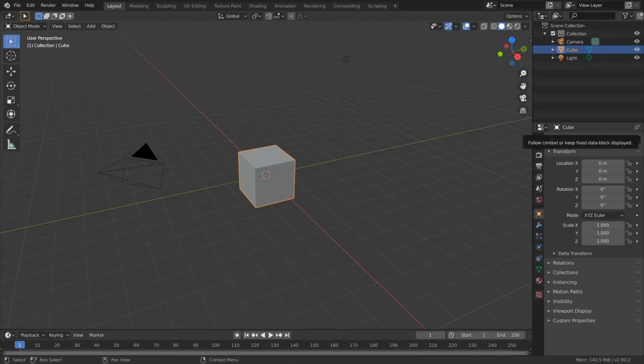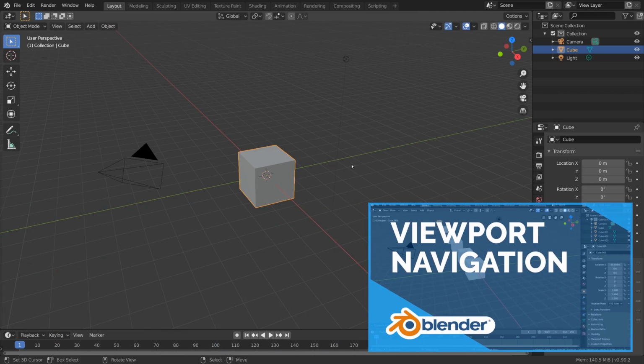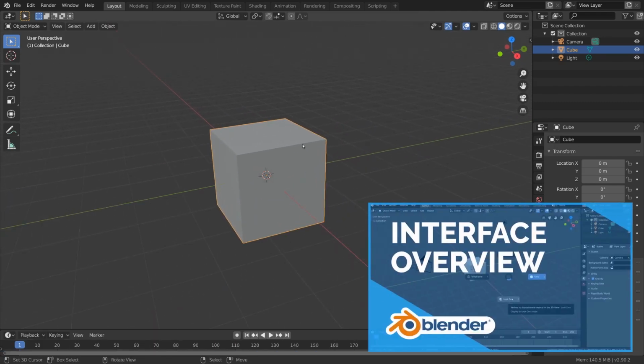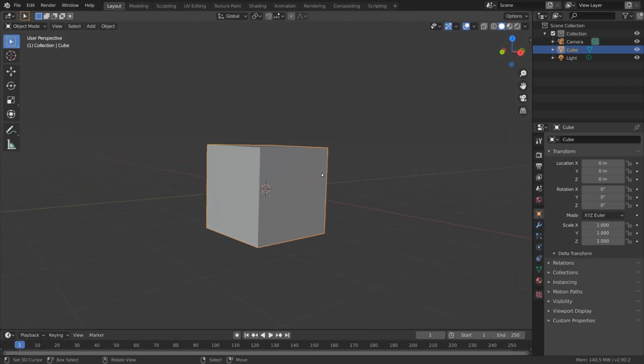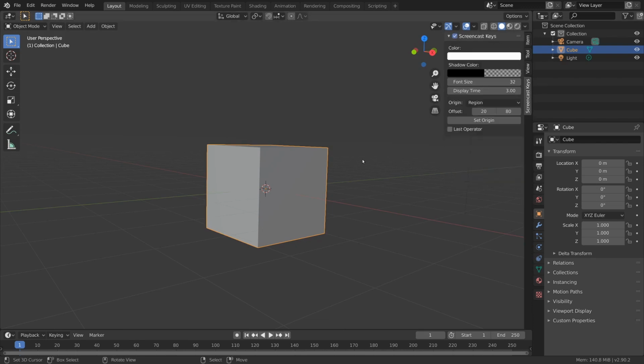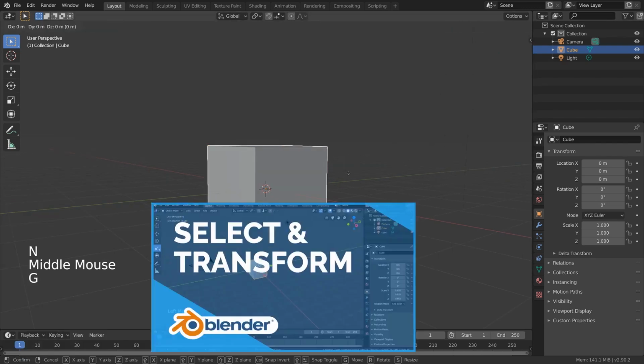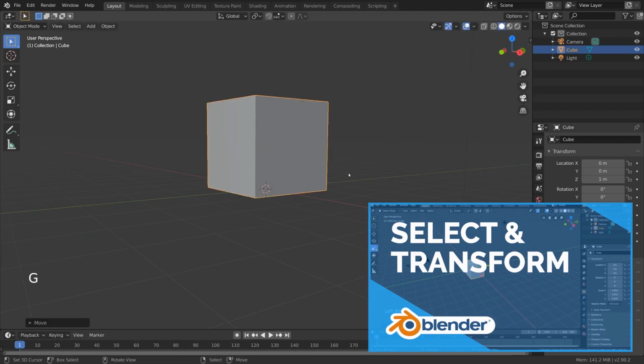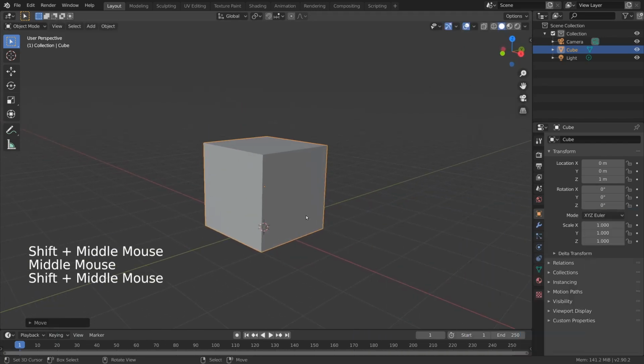So first off, we open Blender, of course, and I won't really go over the basic navigation and the interface of Blender. Watch the first 3 videos of the Fundamental series for that. To create our character, we generally start with the blocking step. This step is to lay out the fundamental building blocks of what we want to create. So since we start the scene with a default cube, let's just build the character entirely around that, just for fun. From here, it's about adding primitive objects with the Add menu.